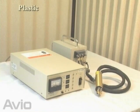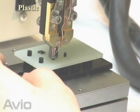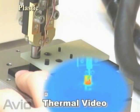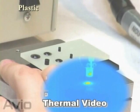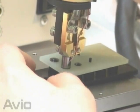This is an example of pulse heat fusing on plastic component. The heater tip is pressed against the plastic, then pressurized and heated. Because of cooling while pressurized, high-tolerant shapes can be achieved without cobwebbing. There's a need for this method as a replacement of screws.